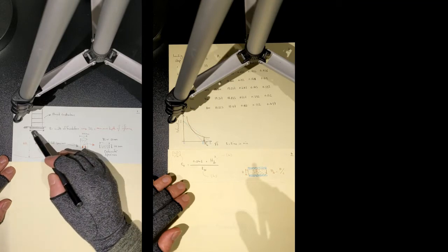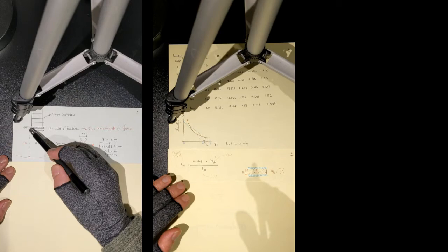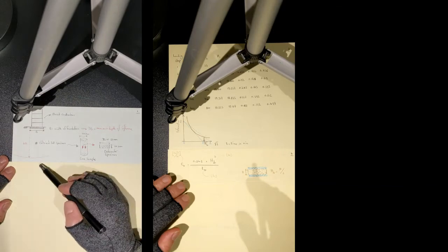Let's say that you have decided on B as the width of the foundation, and this is the 3 times B, the depth of the zone of influence. Now, within this area, you've got a number of boreholes. From one of these boreholes, you've obtained a soil sample, and this cube is your obtained soil sample. Now, I've magnified this. Let's assume that this is a cylindrical soil sample, taken from the ground by the use of a Shelby sampler or U100 sampler, depending on the country that you are practicing in.